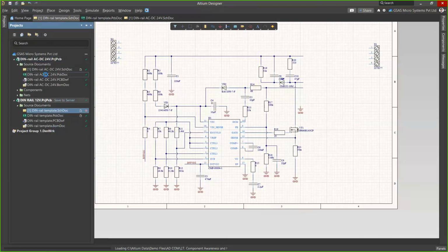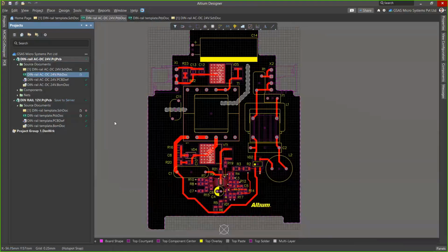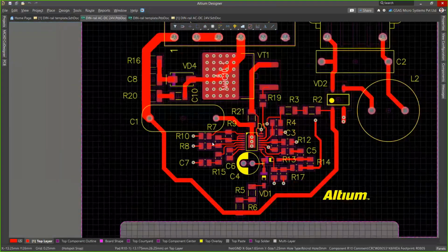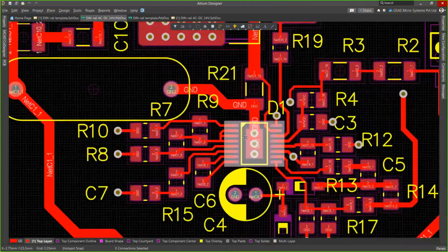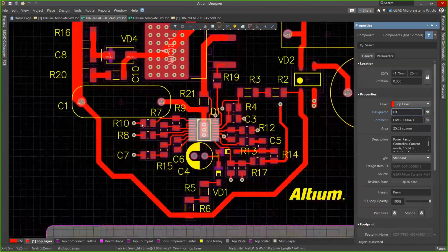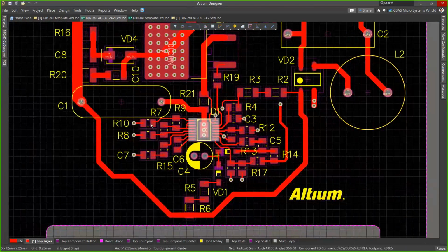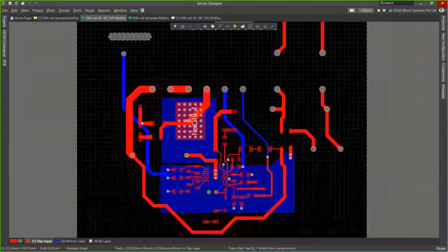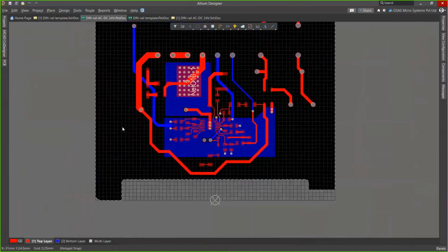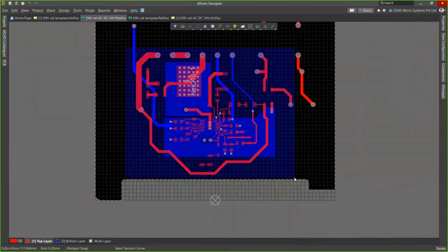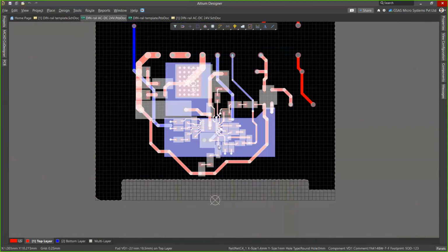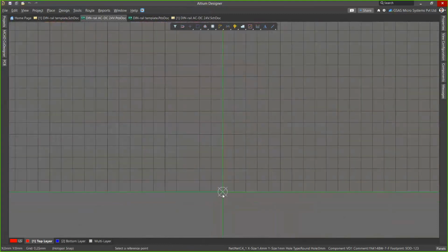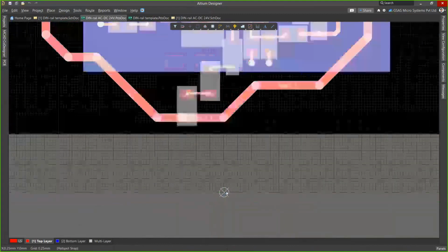Now let us go to that PCB file. See here, this is our D1. This is the D1 which we copied, and this is the circuit which is supporting this particular IC. Now we need to copy. Let us only enable the signal layers. Only these layers you want to copy. Now let us copy this circuit, and Control C to copy, and we use this origin as a reference to copy. Now it is being copied.